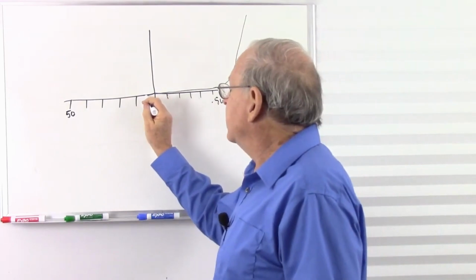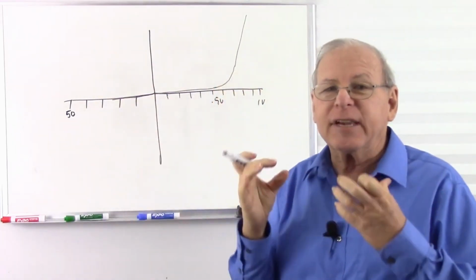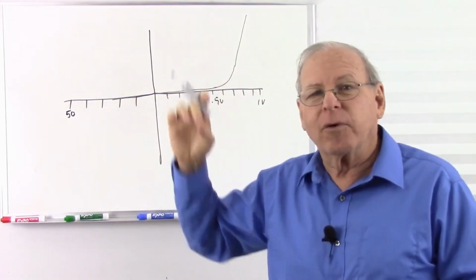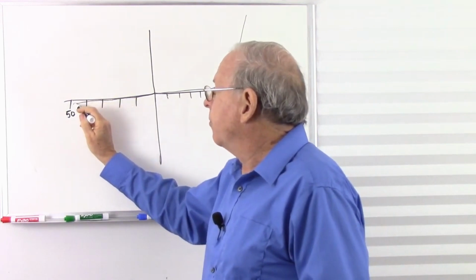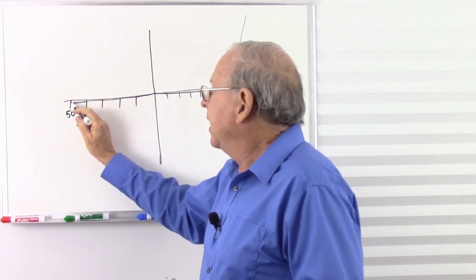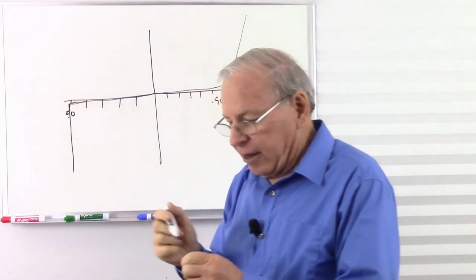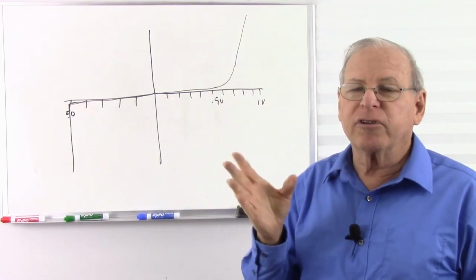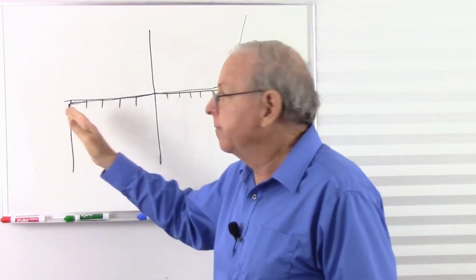We increase the voltage, nothing, no current, no current, no current. Now remember, the current's going to go downward because it's negative current. All that really means is it's flowing the opposite direction. But when we get to the peak inverse voltage, or the breakdown voltage of that small diode, or that regular diode, it's going to suddenly conduct like gangbusters, and it's probably going to burn out unless we have a huge resistor on there to limit the current.